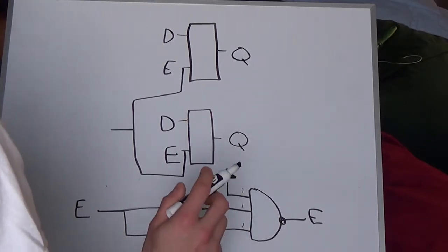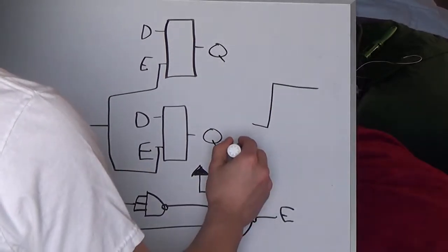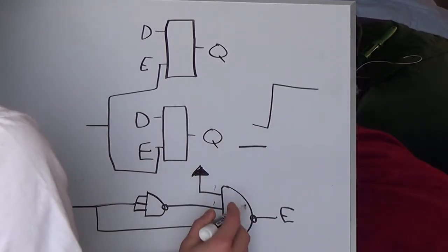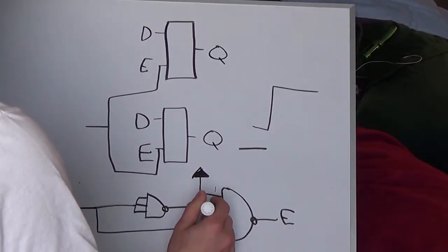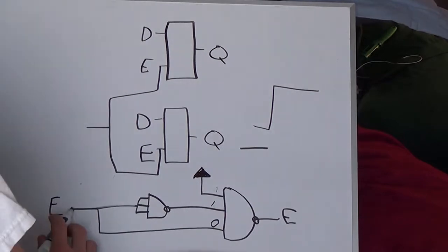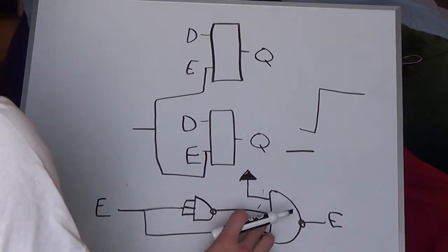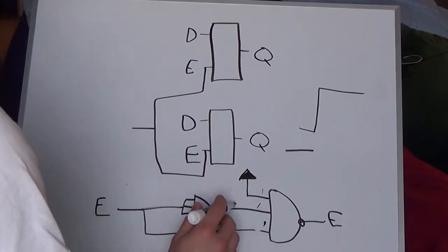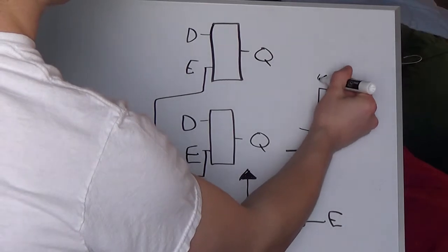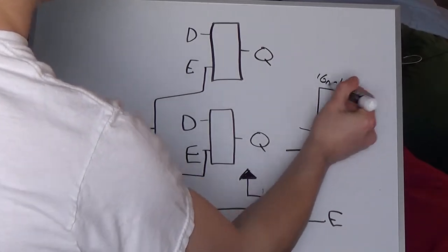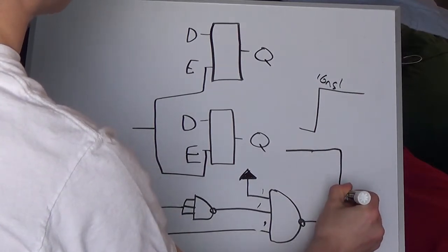And so what you'll see is, if this is your signal, right now the signal's high because this is low and this is high. When this signal here is pulsed high, it sees all 3 of them as high for about 6 nanoseconds before this middle wire here switches to low. And so 6 nanoseconds past when the signal jumps high, that's when it'll drop low.